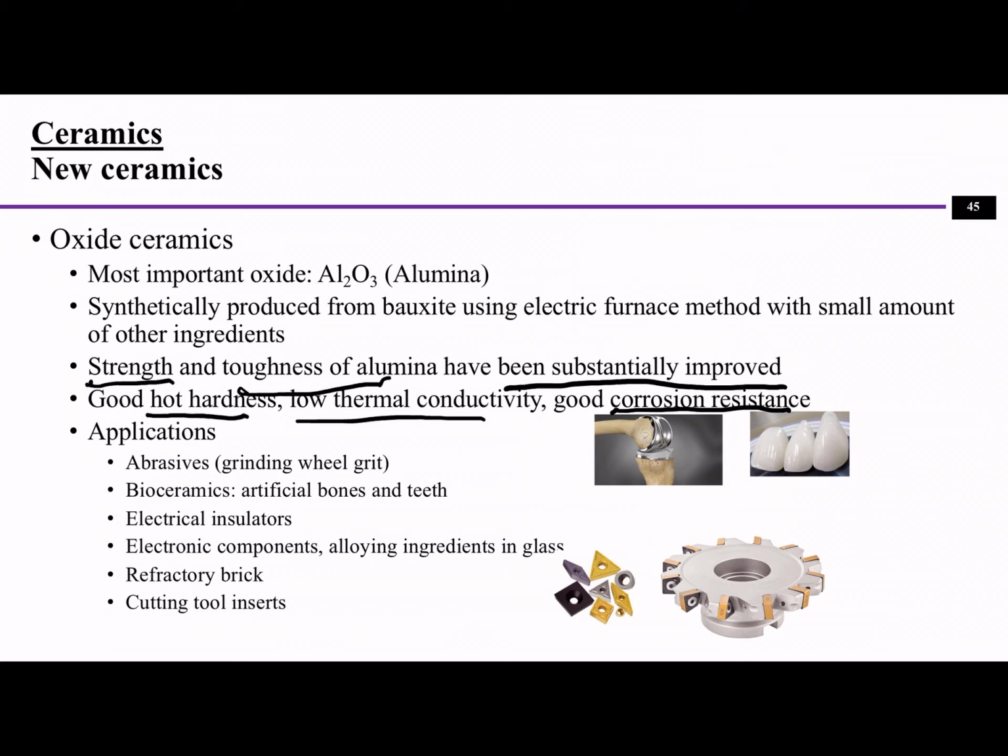For this reason, it has been used a lot in implants and the dental industry, for example, because they can be used as bioceramics, like artificial bones or teeth. Also, because they have very low thermal expansion and can work in very extreme environments, they can be used as cutting tool inserts.